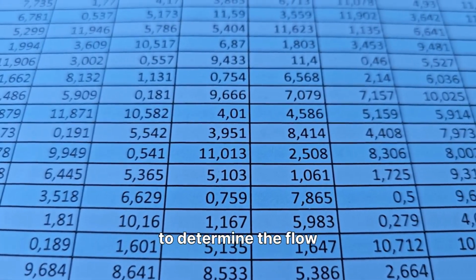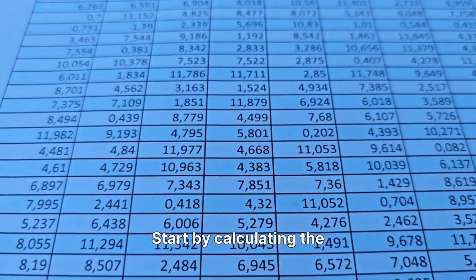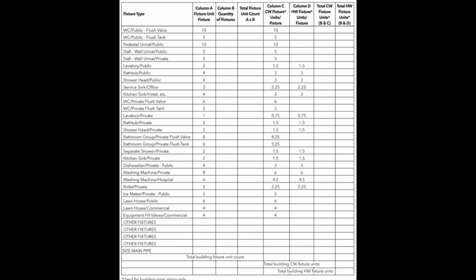The first step is to determine the flow requirements for both hot and cold water. Start by calculating the fixture unit counts. Using a flow calculation sheet shown in figure, locate columns C and D to find the total number of fixture units for the section of pipe being analyzed.